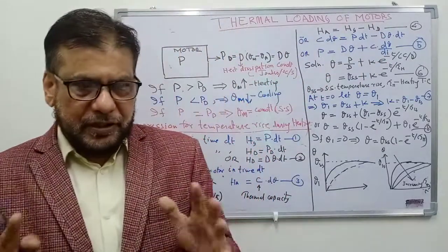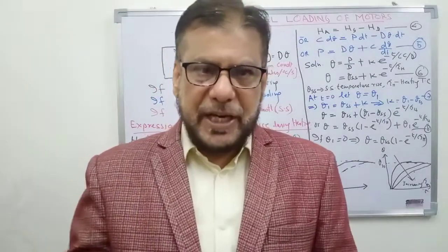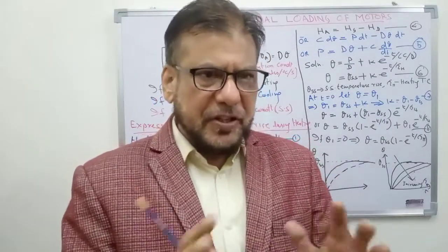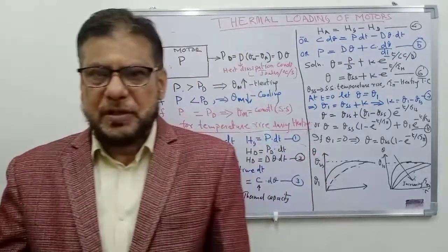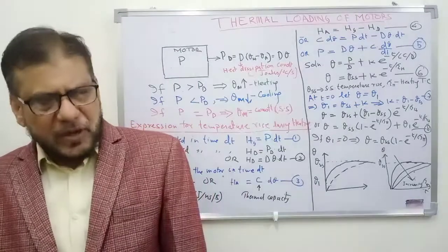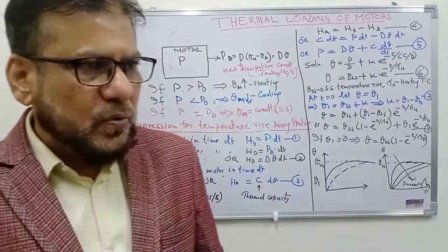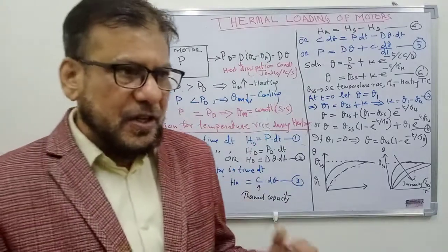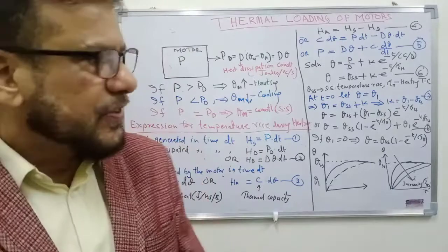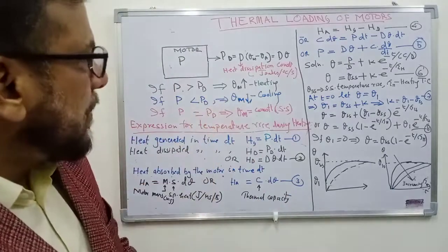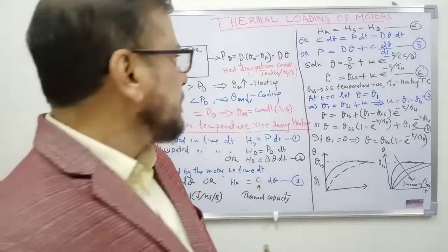When the motor is connected to supply, it starts running and supplies some mechanical load. Some heat is generated inside the motor. That causes the motor temperature to rise. So how the temperature rises, on what factors it depends, and how we can select the rating of a motor for a particular application. So let us first discuss what is the thermal loading and what is the temperature rise when the motor is loaded.